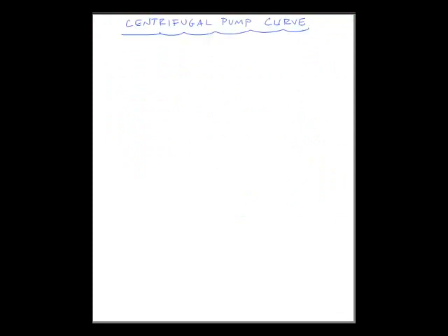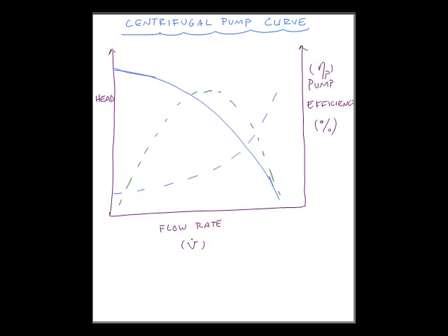Now my pump efficiency varies with my flow rate, or it can. And how can I predict my pump efficiency? Well, I have to go to the pump curve for my pump, and that's figure 14-38. So I'm going to quickly sketch this on our tablet here, and discuss the key points on that.